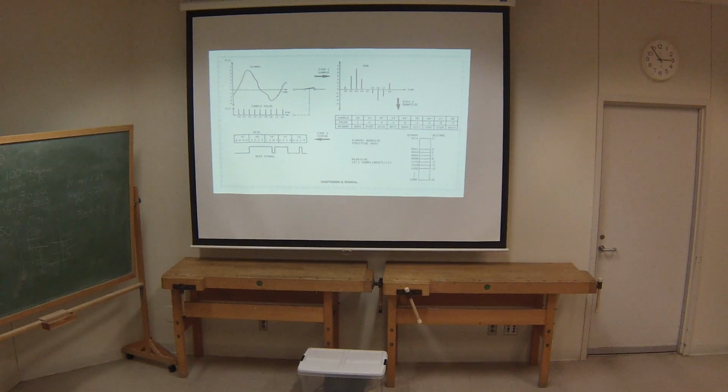And what we need to do next is take that value and convert it to an actual binary number. And that's the actual step into the digital domain. It's called quantization. So you can see here we have a +1, and here the example is a 4-bit number, and we're converting that into 0001.